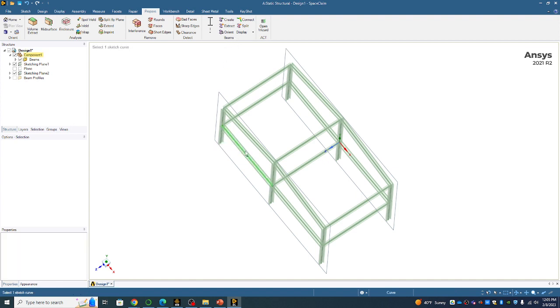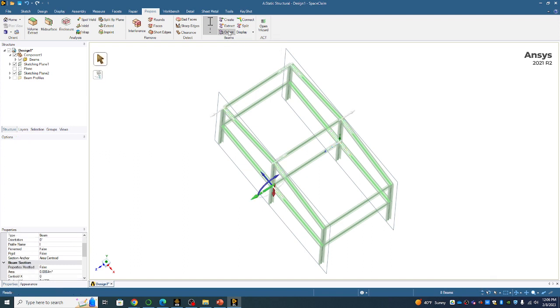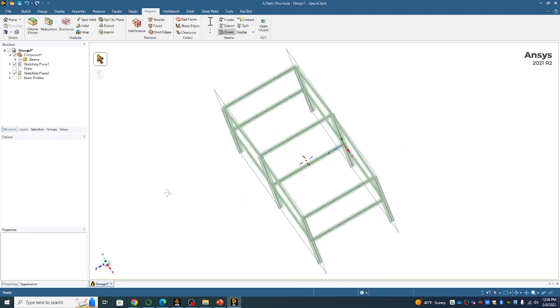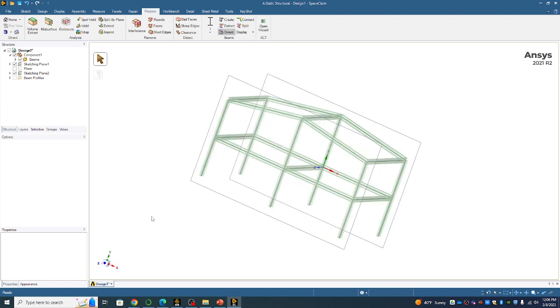So I will choose 1, 2, 3. Use a control click. This 8. So make sure that there's 8 beams that have been clicked. Click orange. So either you can drag it by 90 degrees, or you can change the number here on the left corner, 90. So after you click, you'll see that the strong side has started facing upward. Okay, now we have this structure, and then we can close this, move on to the next step.